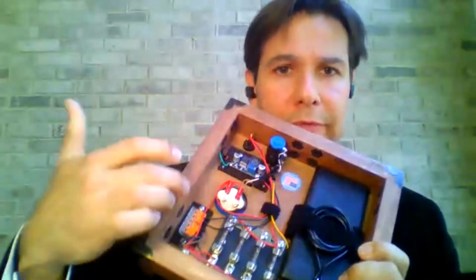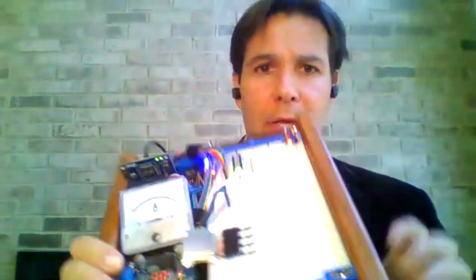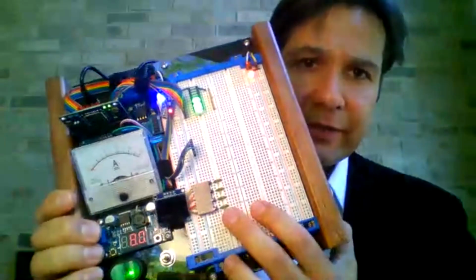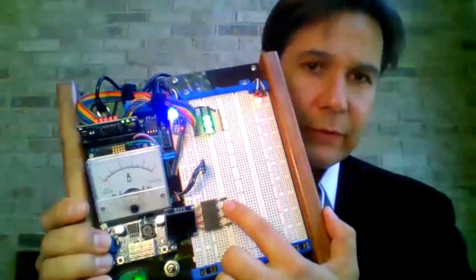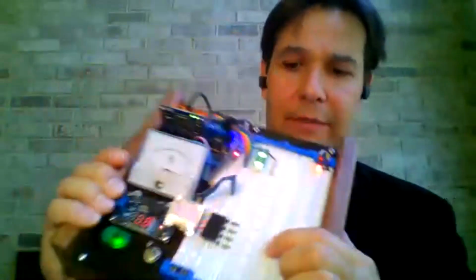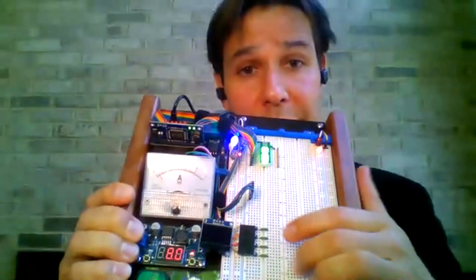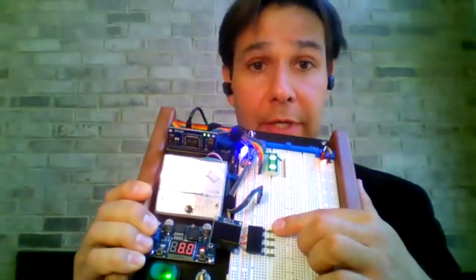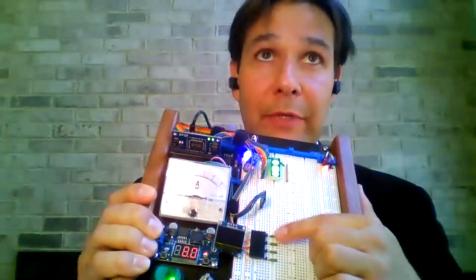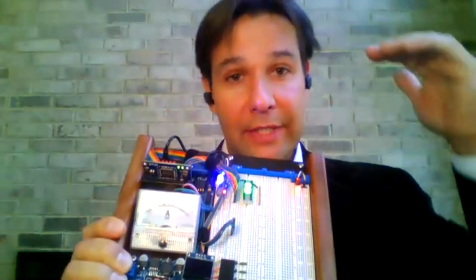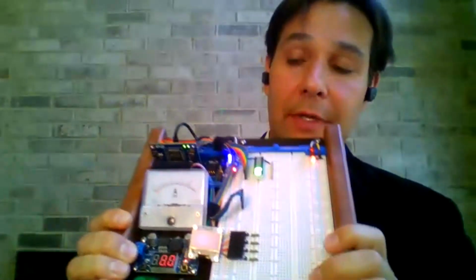So we did blow up a couple of fuses here and there. This was kind of done at the last second just because I found I can get these on DigiKey, but these are actually inline little fuses, disposable, they're painted green, so you can't really tell visually when they blow. But I put these in line with the pins we use most often, pin 0 through 3. I wound up using 500 milliamp fuses because as you get down to these lower value fuses, the resistance really starts to spike up. So if I went with like a 100 milliamp fuse, it would have been like 10 ohms, and that might have messed up some of the signals coming out of these pins. But that's one thing I was really trying to protect.